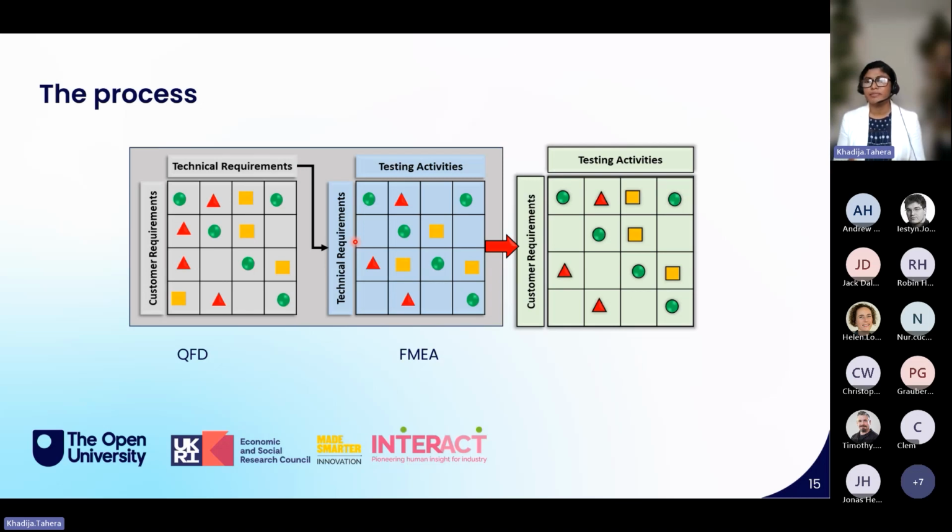We are also identifying the verification and validation testing, but here again the focus is on testing. What tests are we going to do to mitigate the risk, so that we can prove ourselves, through the design change or whatever change, that this risk doesn't exist? There are many other tests we implement to confirm that the failure mode we identified in FMEA is the actual failure mode. So we do physical tests, and then the government physical tests, legislation-wise, depending on which sector you are in, standards, and all sorts of tests we have. That's up to you how you decide, but we identified the testing activities you would need. Again, we simplified this process and identified the key testing activities for the system level.